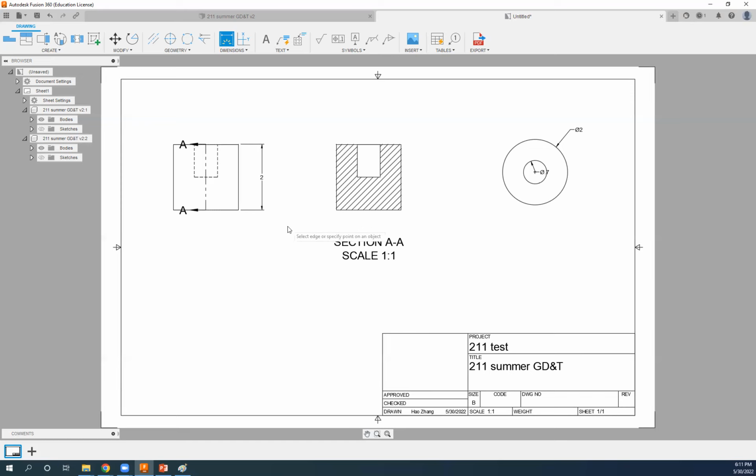Well, if a designer wants to replicate this drawing, there's one dimension missing. That is, what is the length of this one, right? What is the depth of this hole? Then I also need the dimension for this. Maybe I'll just specify it from here. Depth of the hole. Right, put it here. Now we're good. All right, I created all the dimensions.